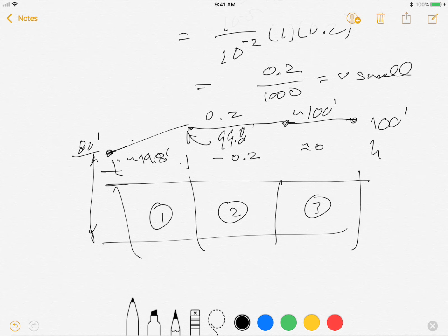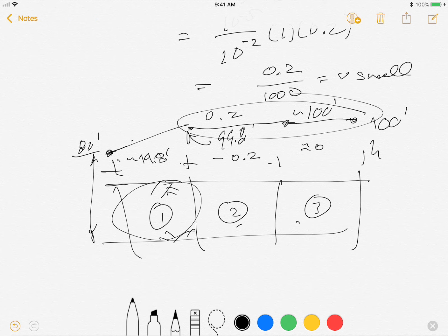Okay. Now taking a step back from this, what have we learned? Well, we've learned that the permeability is very important in terms of energy drop. And so if you're trying to drop energy, you're not dropping any significant amount of energy in these more permeable materials. But that clay material over here is permitting you to drop all of this energy through that material. So as you're looking at designs, you might want to drop energy. You want to control how energy is moving through soils, and one way to do that is to use clay. That will help you with your various designs.